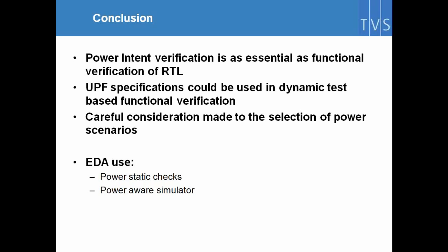It's probably true for most things. It's probably true also for the UPF. The UPF, although it's power intent, has some impacts on the functional side. If you're not able to switch on a block, then your design is not going to work. So this should be carefully taken into consideration.